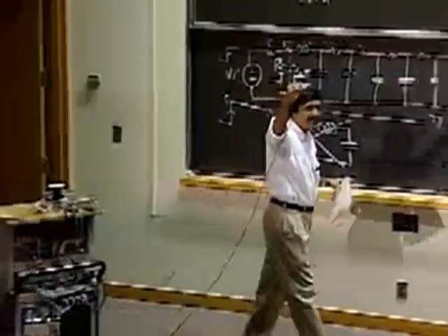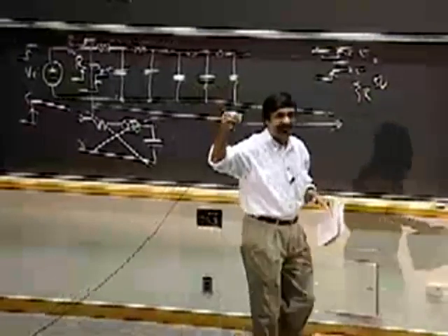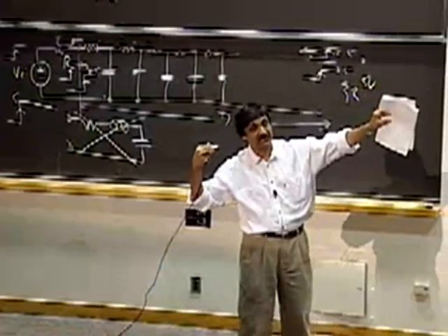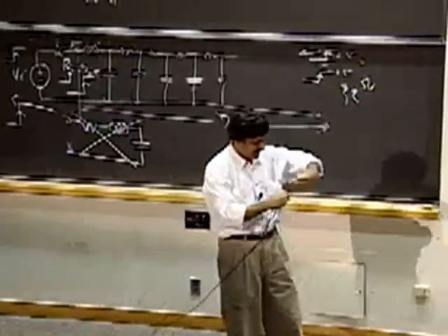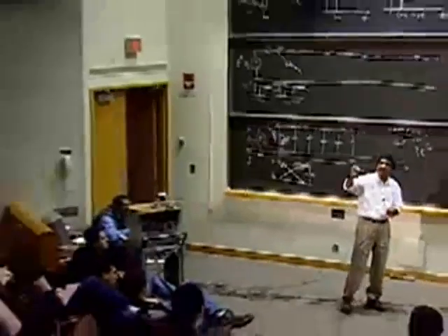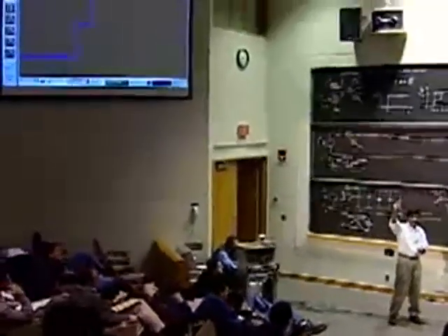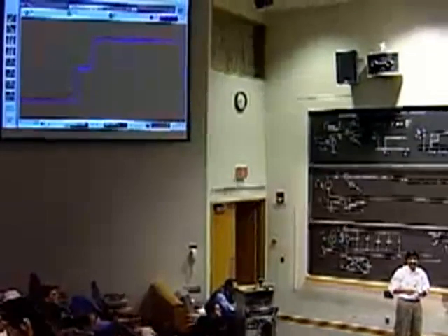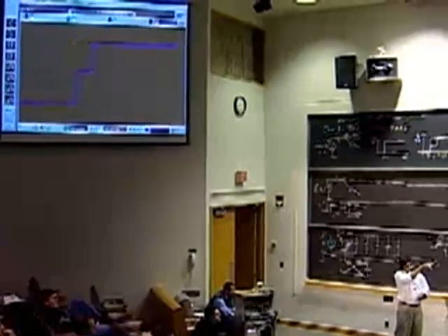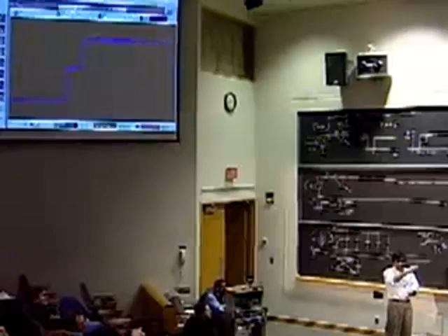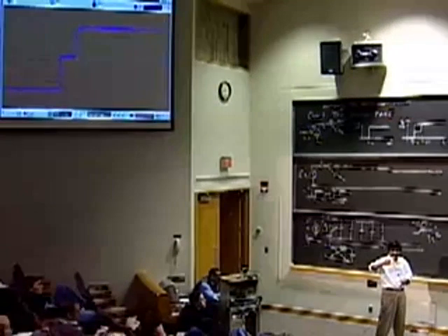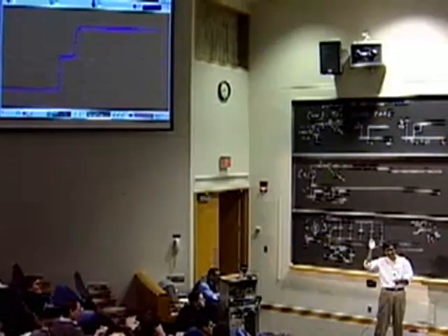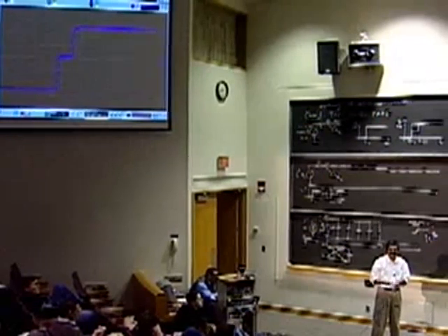So this is the end of the cable. If somehow you could watch this and that at the same time. So what I'm going to do, and this is a resistor R, I'm just going to plug it in. If the fates are smiling at me, what should you see there? What should happen is that the second jump from 2.5 to 5 should simply go away, and it should just go to 2.5.